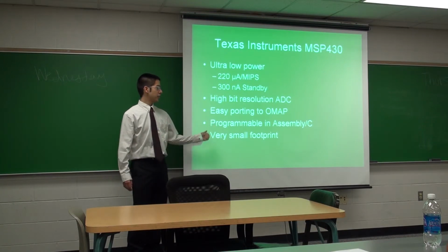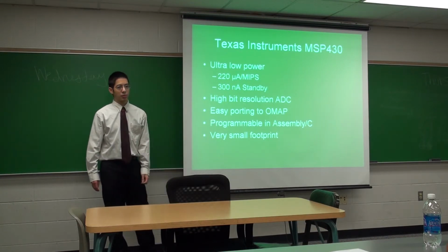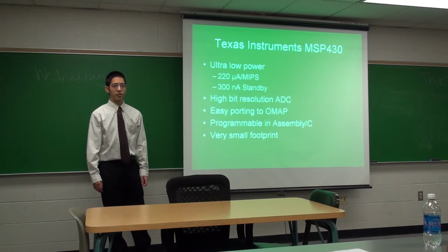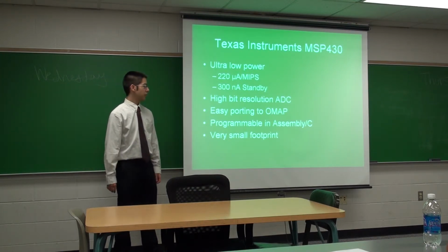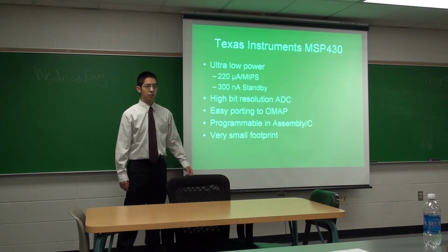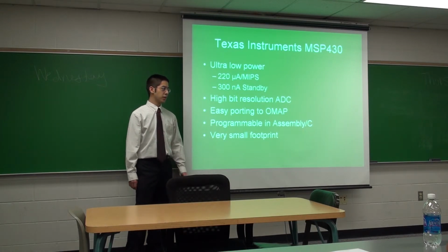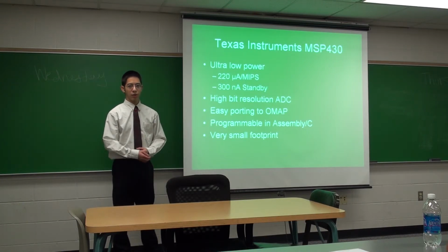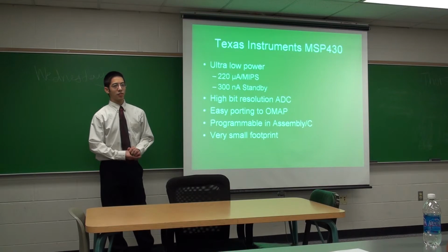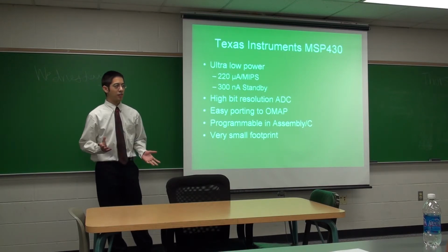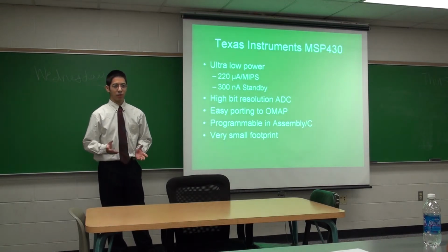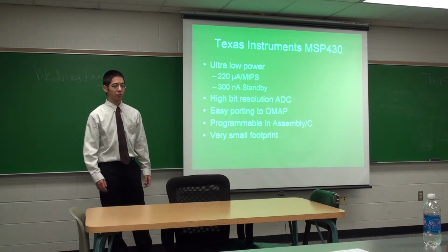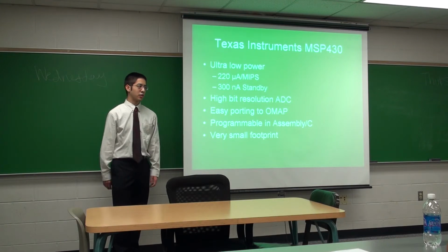The final design is to port to an OMAP, which is a pretty popular processor inside cell phones such as the Motorola Droid X. The microcontroller is programmed in C or assembly, which can be ported almost directly to the OMAP processor with very little effort. And this processor also comes in various sizes, so we can test using a regular DIP processor, and then in our final design we can switch to a very small scale and solder them to our PCB.